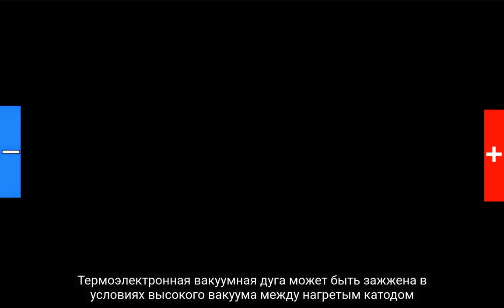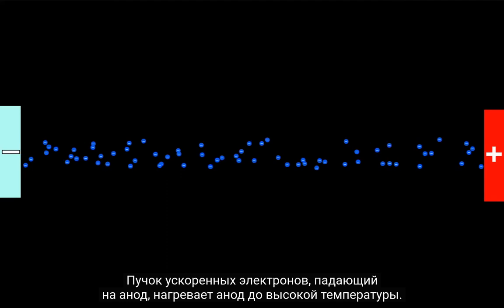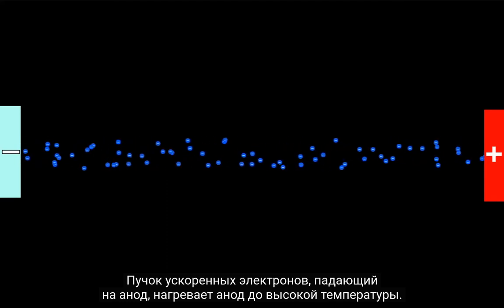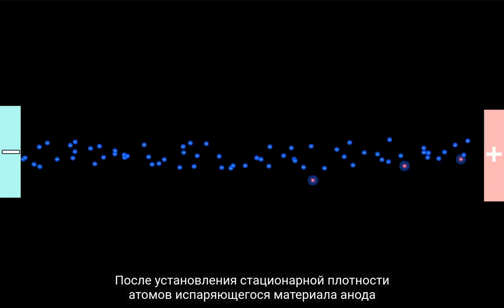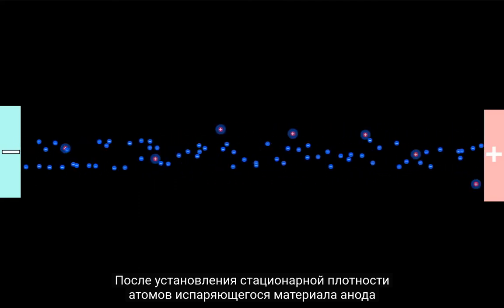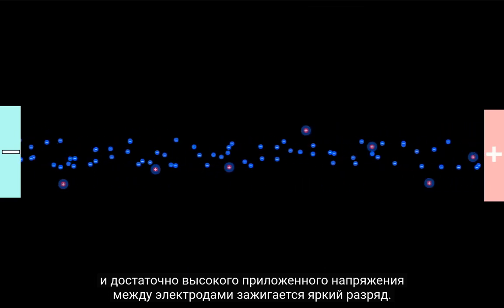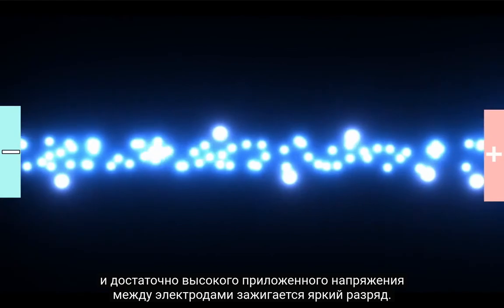A thermionic vacuum arc can be ignited in high vacuum conditions between a heated cathode and an anode. The accelerated electron beam incident on the anode heats the anode to a high temperature. After establishing a steady-state density of the evaporating anode material atoms, and the voltage applied is high enough, a bright discharge is ignited between the electrodes.